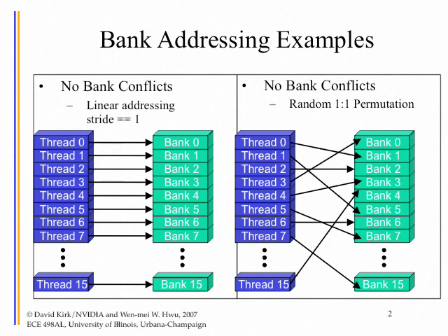And how is this done? This is done with a crossbar switch. So the hardware will figure out the pattern and set all the switches in the crossbar so that all the banks will be connected to the right processors with that switch. Okay, it's a fairly expensive kind of design, but it's pretty standard in industry today.